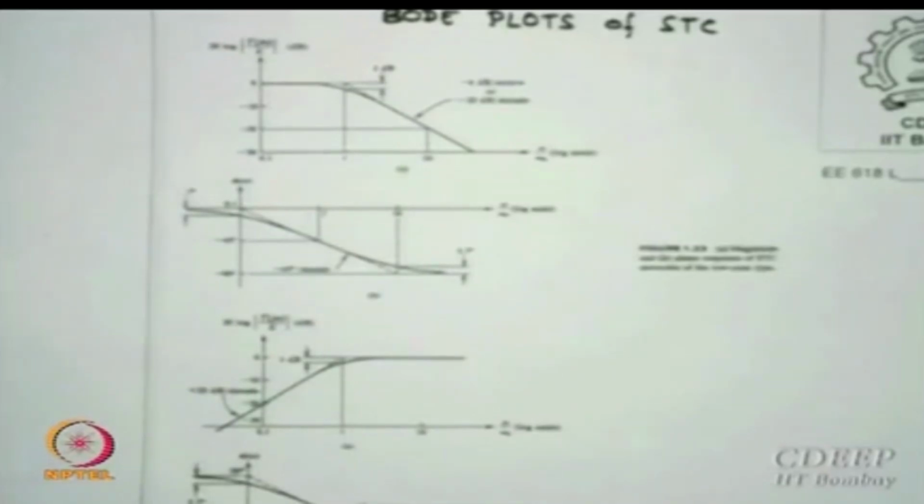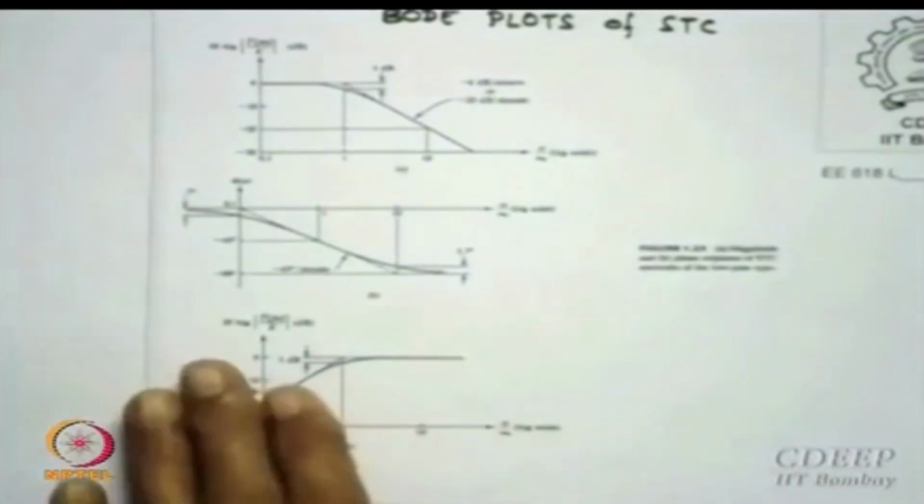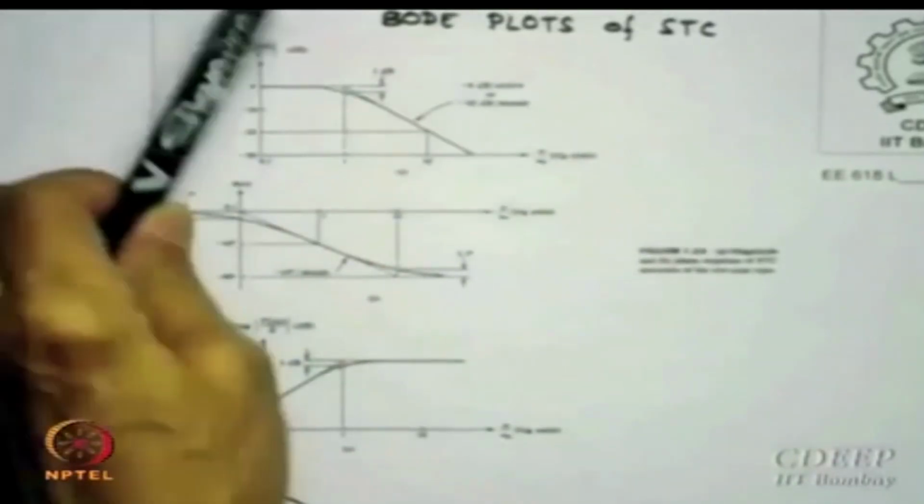Normally an amplifier response is closer to a mixture of a high pass and a low pass. Initially it rises, then becomes constant and then falls. So this precedes this and you have a normal gain. But for an op-amp this does not exist. The gain even at 0 is finite, because that is the difference between normal amplifiers and an op-amp. At 0 frequency, also DC can be amplified by an op-amp. Is that clear to you? And therefore normally the response is exactly like this, it does not follow here.